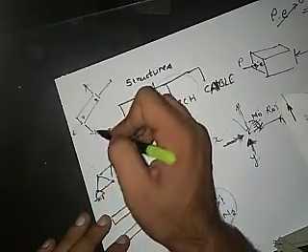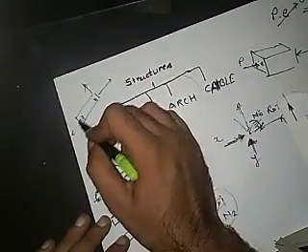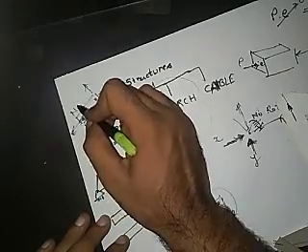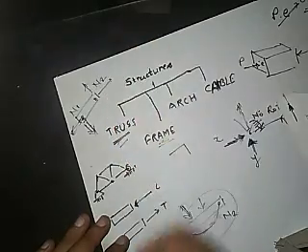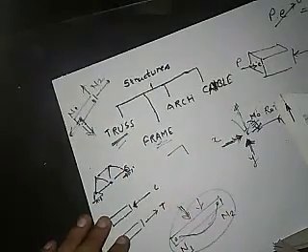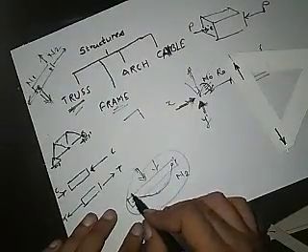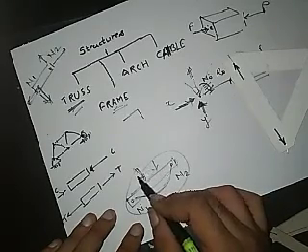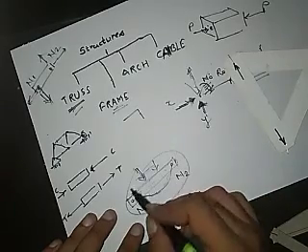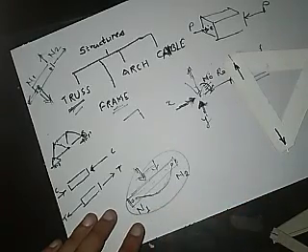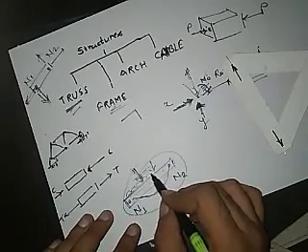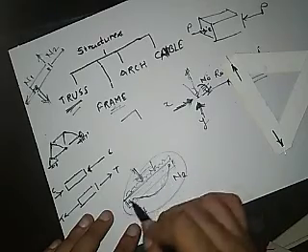Okay, these all will act along the node. Say this is node 1 and this is node 2. All the loads will act on these two nodes. So we know that in this case, if there is no load acting on it, it will sag. Why? Because it has its own weight, which can be analyzed under a UDL, uniformly distributed load, between these two nodes.